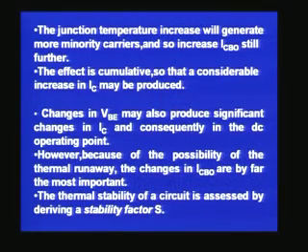This is what is called thermal runaway. The transistor runs away with larger and larger current, initiated by the temperature variation, and the temperature variation increases IC, and IC increases temperature. So each one of them helps the other and they both run away, and finally we end up with the transistor getting spoilt. So we must make sure the thermal runaway condition is not generated in any amplifier. That is one of the very important things. That is why people say ICBO is a much more important parameter to worry about than the VBE.